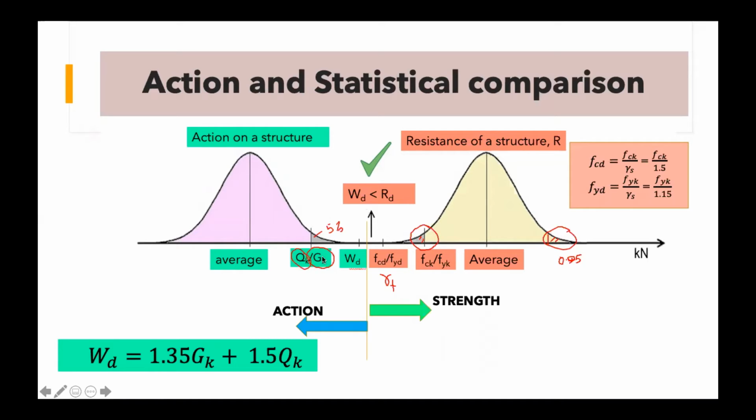Therefore, our design action WD, a combination of QK and GK, must be less than the strength of the building, here the strength of the concrete and also the strength of the steel. That is the idea of the design, the philosophy of design. So WD here is the safety factor.